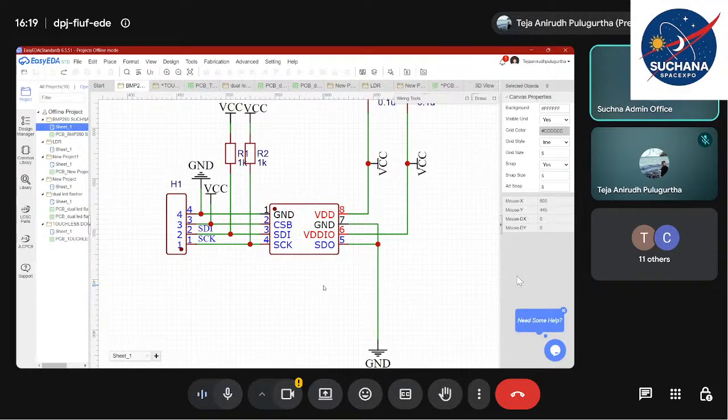Only two I2C addresses are possible, either 0x77 or 0x76. So let's say you have five BMP280s that must be connected to a single microcontroller. For one, you can set 0x77. For another, you can set 0x76. Still, we are left with three more BMP280s.